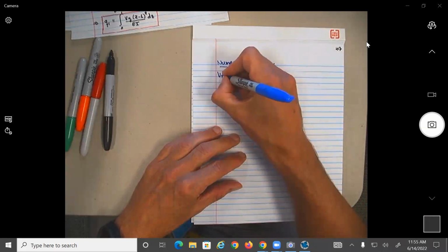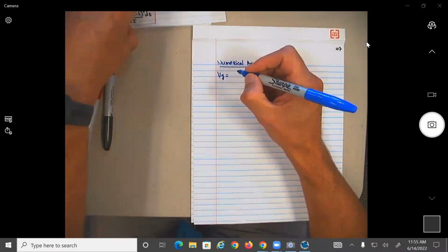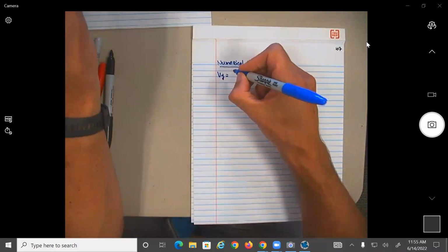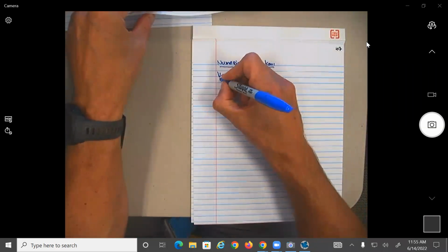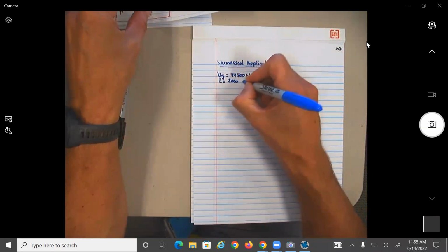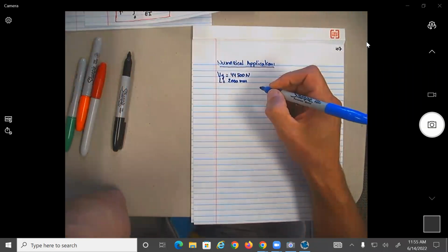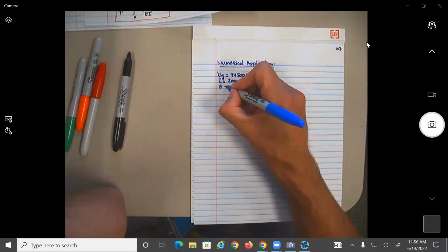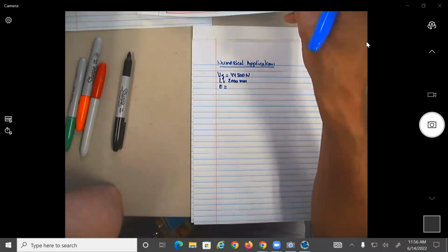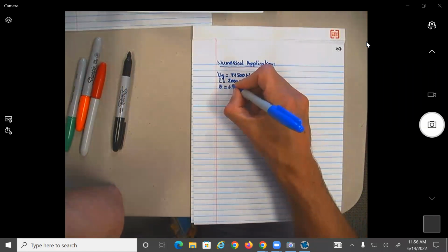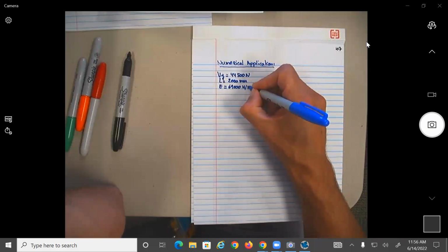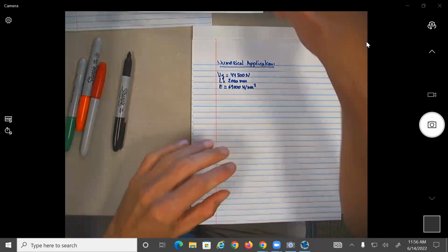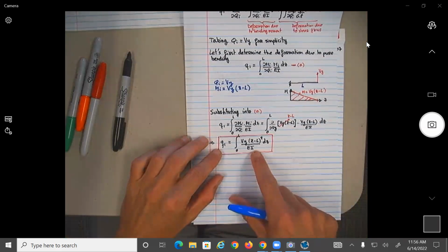So basically Vy, how much is Vy? I think it's 44,500 newtons. L is 2,000 millimeters. And E, oh, we forgot something here. E is equal to 69,000 newtons per meter square. But what do we need? The I. Okay, I forgot to calculate. I should have done it first, but yeah.